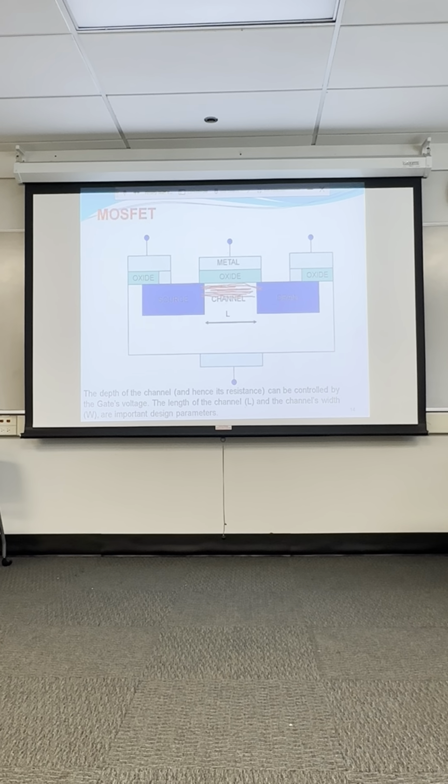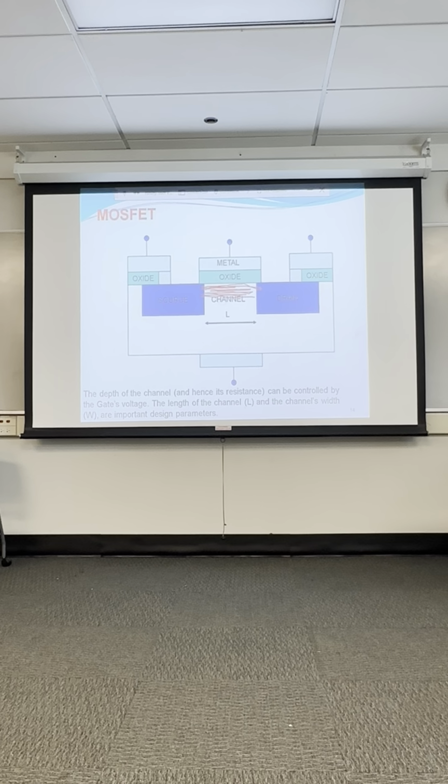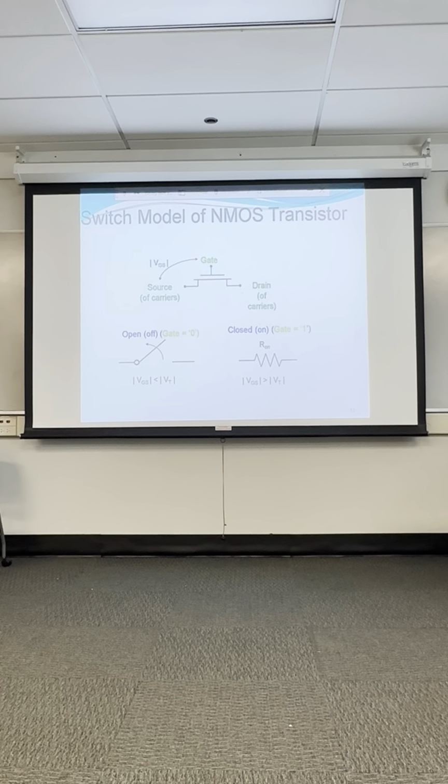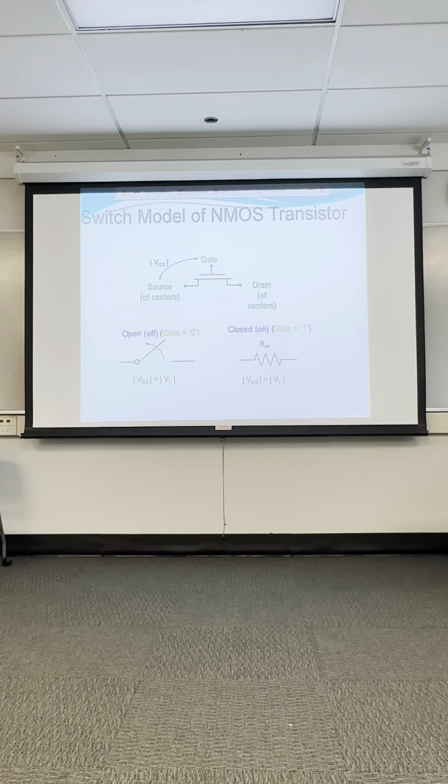What happens to this channel when the gate voltage is 0 volts? It doesn't let it flow. The channel collapses. Okay. When gate voltage is 0, this channel collapses, and the enhancement MOSFET returns to an off type switch. So this MOSFET, here's another MOSFET symbol you might come across. It doesn't even identify the source and the drain.